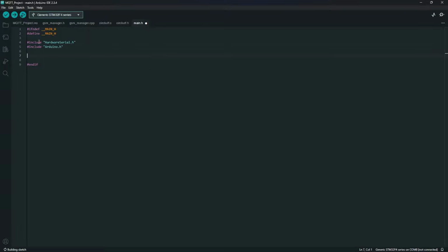From there, as I said earlier, we're going to be including a button press in this example. So I want to define a way that we can measure the time that a button has been pressed. This is going to be done as a software debounce, so that when we press and hold a button it doesn't register as multiple presses, or even if we just press it once, that it doesn't measure as multiple presses. So I'm going to name the function millisecond since, and I'm going to use the built-in Arduino millis to determine what millisecond since is.